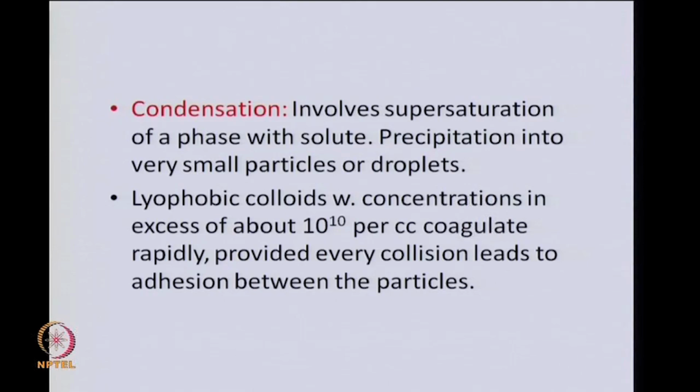It is here that it might be worthwhile to know that in condensation, which is akin to crystallization, the supersaturation can itself lead to two different ways of forming these submicroscopically small particles. One could think of nucleation here. We may have ultra high supersaturations leading to spontaneous formation of molecular clusters, which are few thousands or few tens of thousands of molecules forming aggregates as a result of thermodynamic fluctuation. Such kind of clusters would always form when we have very high supersaturation.